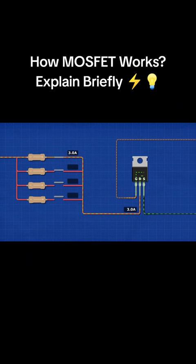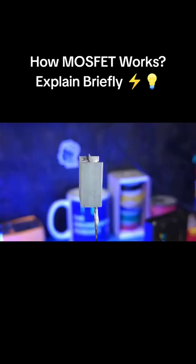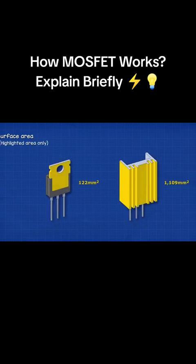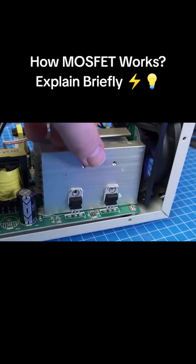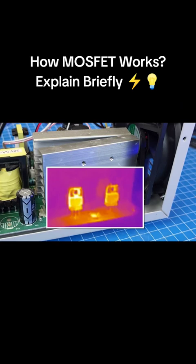Some electrical loads have a high current, which causes the Mosfet to heat up. So we attach a heatsink, which increases the surface area with the air and helps to cool it down. For example, this DC power supply uses Mosfets. The Mosfets are attached to some very large heatsinks. Without them, they quickly rise in temperature.